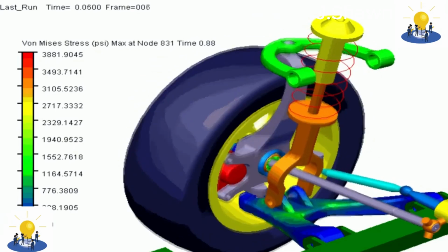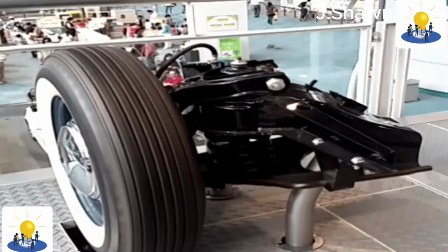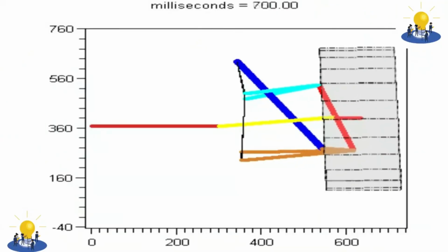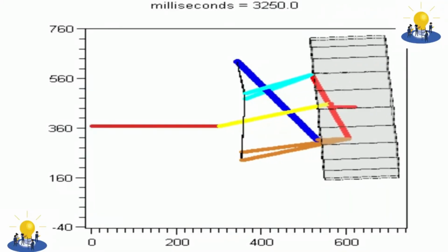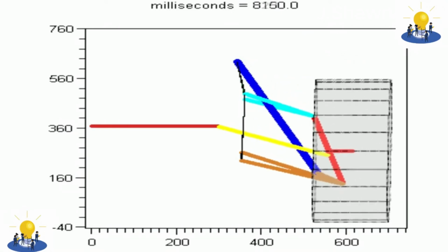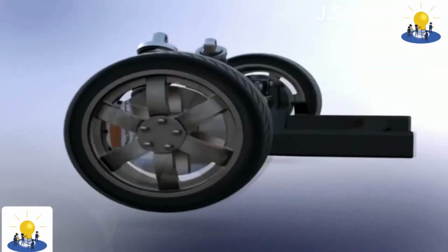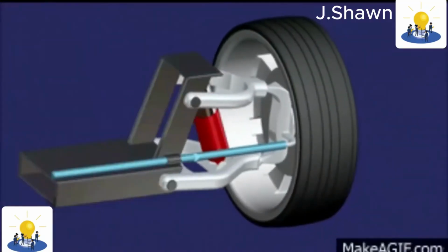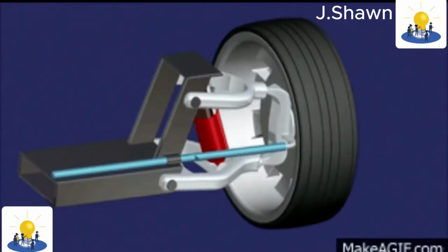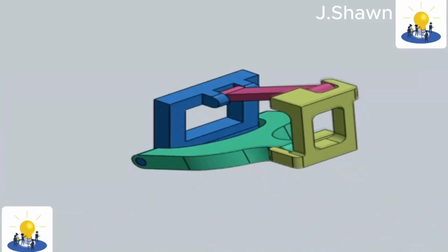In many racing cars, the springs and dampers are relocated inside the bodywork. The suspension uses a bell crank to transfer the forces at the knuckle end of the suspension to the internal spring and damper. This is then known as a push rod if bump travel pushes on the rod, and subsequently the rod must be joined to the bottom of the upright and angled upward. As the wheel rises, the push rod compresses the internal spring via a pivot or pivoting system.